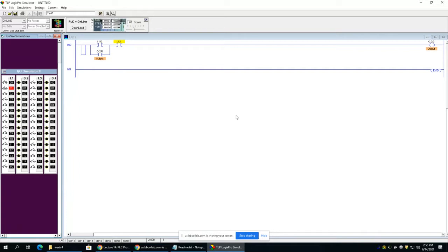So this is a circuit you're going to make in lab, but what you got to do is explain it. You got to walk through step by step and explain what each of these things are doing. And just to say it in words, just to prove to me that you understand what we mean by start, stop, and latch, and use the terms logic continuity, logic flow, and all of that stuff. So the best way, guys, is just to kind of play around with this.